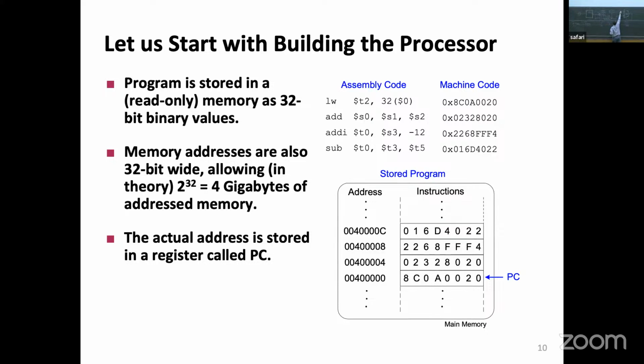I will take the register address from here, get its content, add it to the immediate, and I have a value. Okay? That looks very good. And now I have a 32-bit value. What is this value? Well, this value is the address that will end up going to the data memory, which I'll put here. So this is the data memory. And the data memory has an address input, a read data, and a write data, and also has a write enable, as well as a clock somewhere.